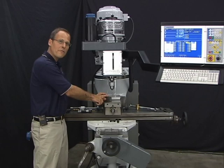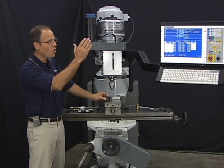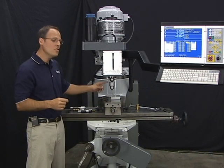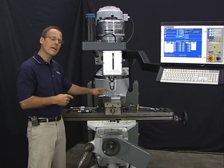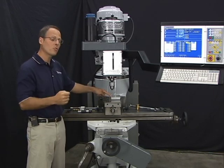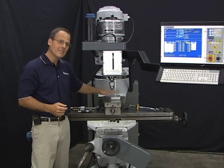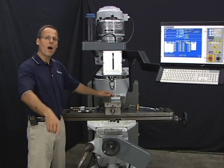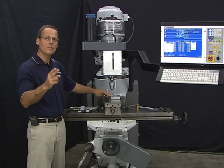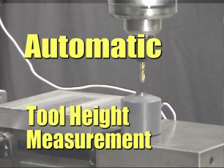When we were using the reference position and touching the tools off, all we were doing is telling the control the difference in length between all our tools. Now, when I use that same tool to come back and touch off the top of my work to set a Z0 position, what's great about the reference tool method is all those other tools are automatically set to that position as well. So I only have to touch off the top of my workpiece once with one tool. And it can be any tool that's set up in the tool library.